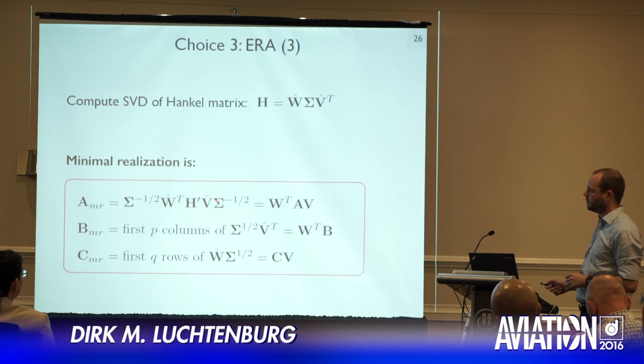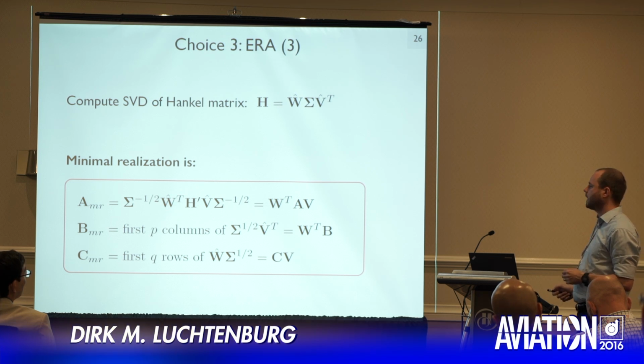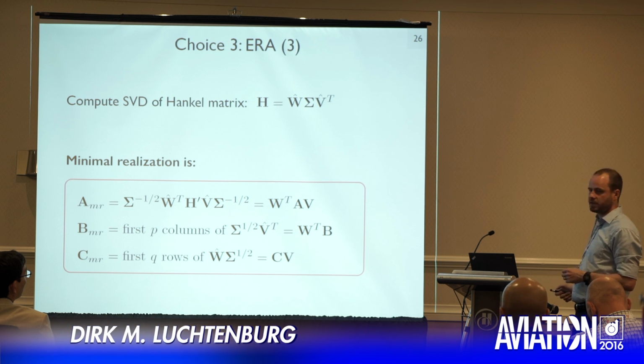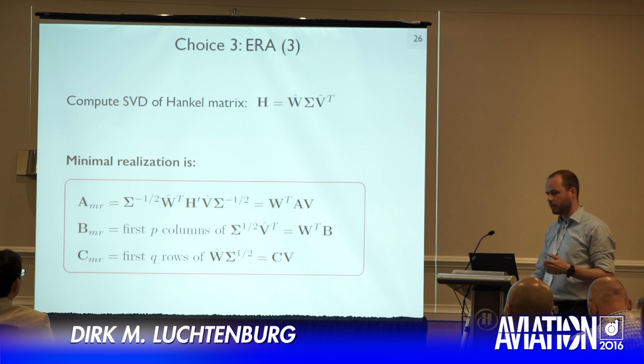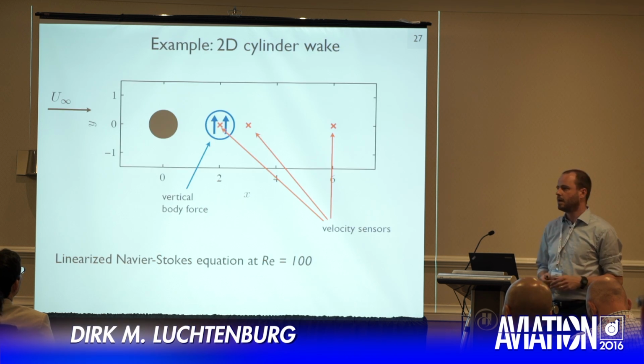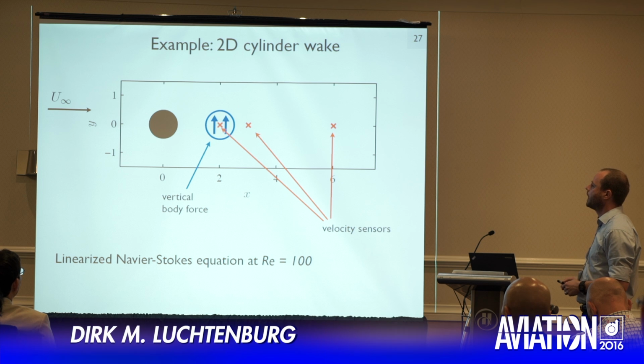And you see this other Hankel matrix showing up here. It turns out, if you work this out, that this is completely equivalent to the projected matrices that you get out of the procedure with balanced BPOD. So this is really great news. Now we have something that can work in an experiment.